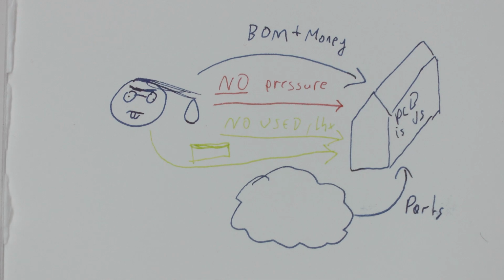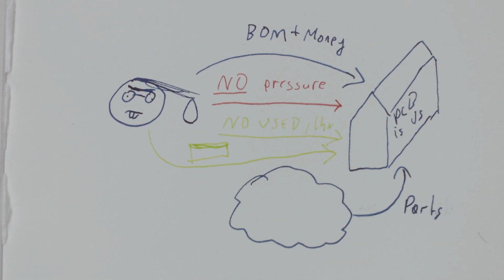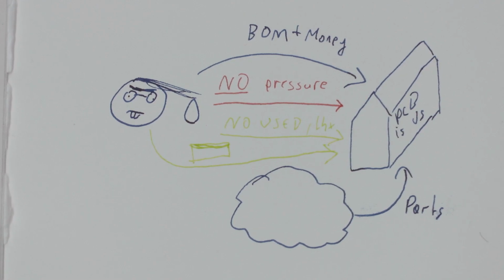And yes, in some special cases, the only way to work around the problem is, as you see here, sending the components. There are some parts which are just known to be notoriously commonly faked, and if you have an open conversation with your vendor, they sometimes ask you, please slip them in an envelope and send them. I've done this a lot for all of my contract manufacturers in the past with clients that allow me to do it. Sometimes literally I just buy the components off of OEM Secrets, put them in an envelope, write on the outside documents €5 and send them to wherever they have to go.